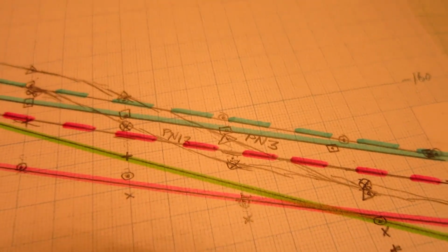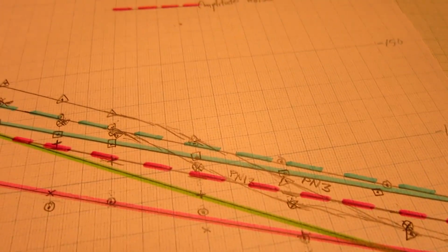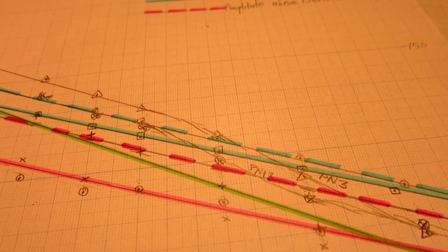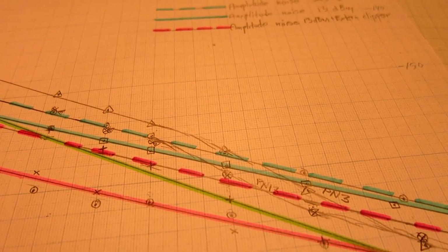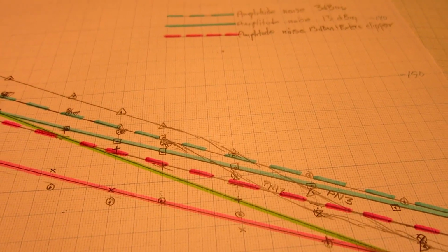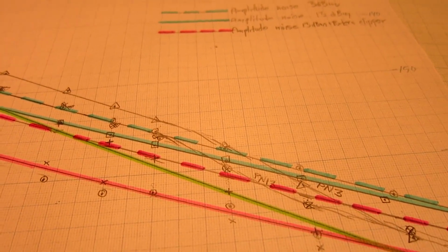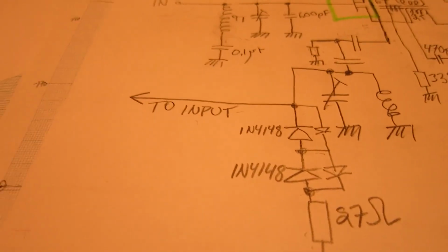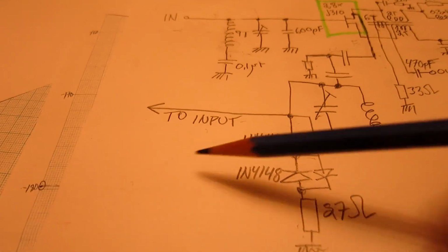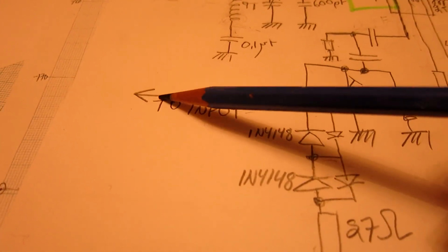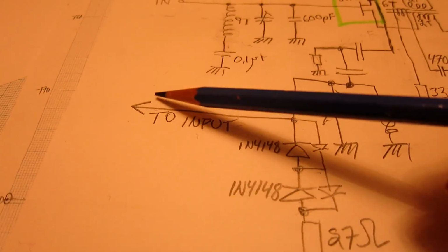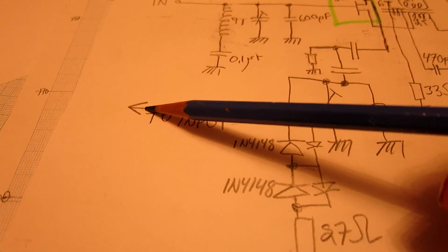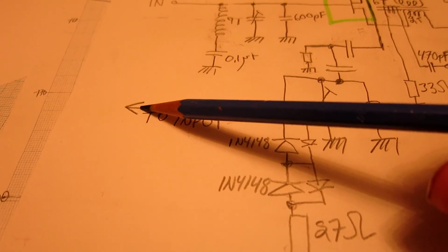So I will look at making a much harder clipping, because quite some time ago I had a very hard clipping and it looked like AM noise was reduced drastically by that. I have put a dummy load at this point where I have been looking at the sideband noise up to now, and this is the normal feedback for making an oscillator.